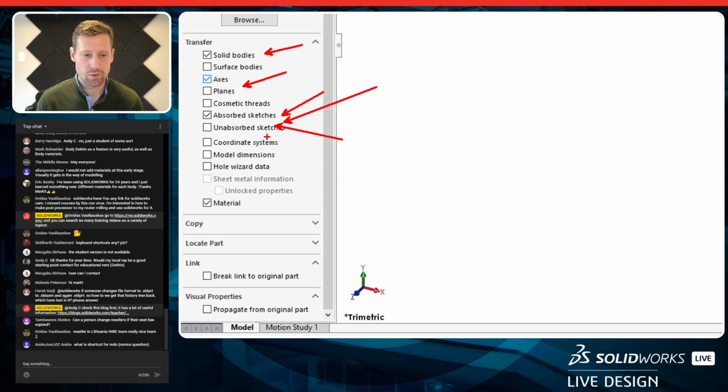This is incredibly important, especially for some of these master modeling techniques, because in the individual part files, when you're creating those manufacturable features, sometimes you're going to really need to go back to the original master model and make sure you're making references and relations to those sketches that you had in the past. So those are going to be really useful, and this is something that wasn't available in any of those other methods that we discussed so far.